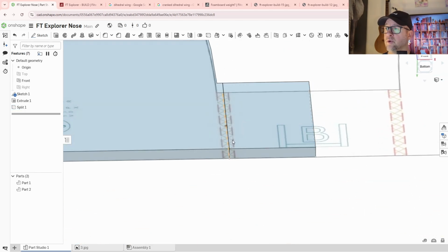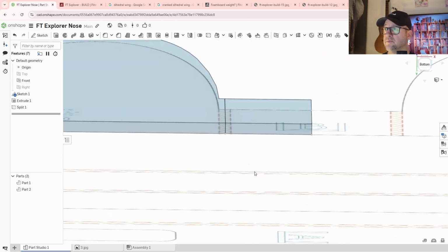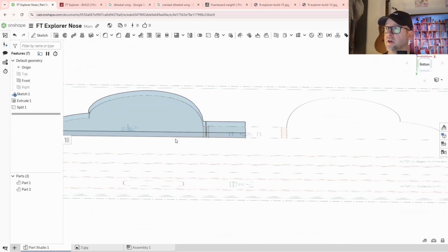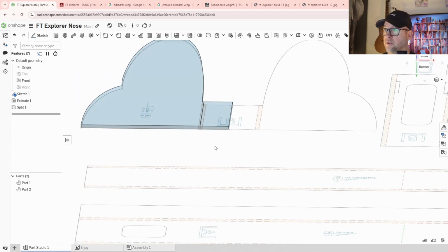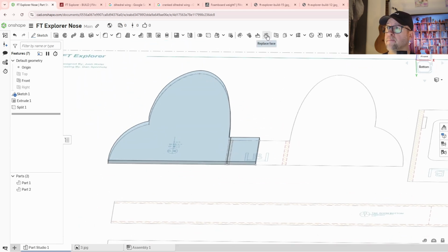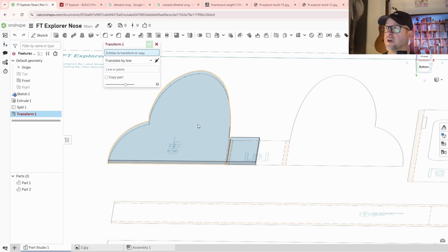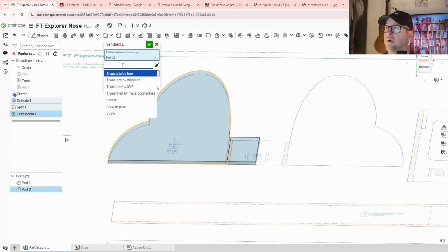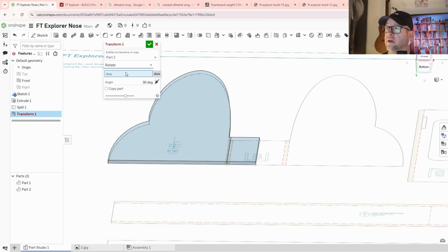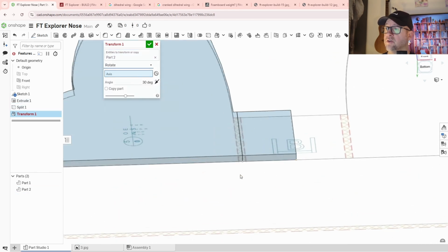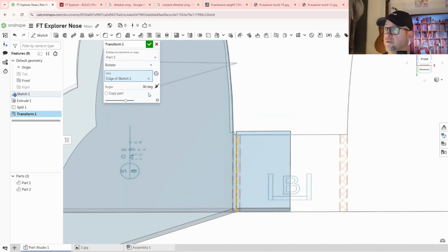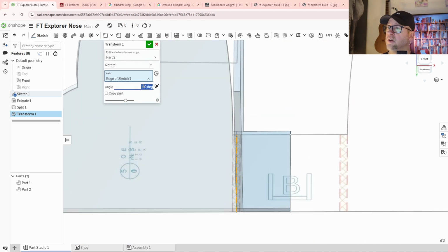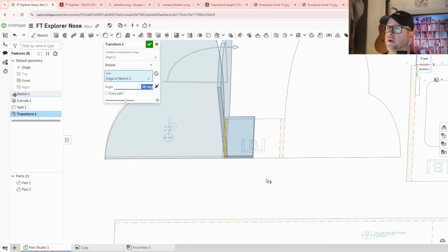So now I can rotate this. This body right here, I'm going to rotate and then pull it up, straight up. Okay, here we go. So we're going to do a transform of that. Okay, here's transform right here. So we're going to take this and we're going to rotate an axis, and the axis is down here. It's this edge right here, and we're going to do a -90, I think. -90. Yep, perfectly. It takes us straight up.